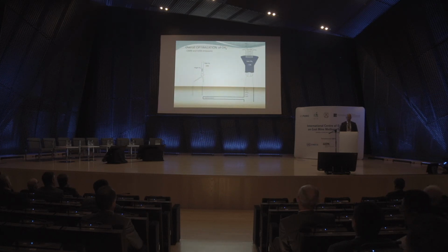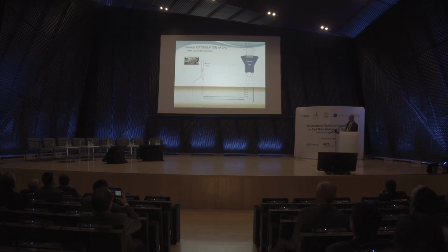So when you look at your installation, you want to optimize it. Well, you look at what concentrations and volumes you have in the drainage. You look at the concentration of the ventilation air. I would say you first look at installing gas engines, because that's the most cost-efficient way to use the mine gas. And then you look at, if you really want to reduce the emissions from coal mining, then you have to address VAM, because it represents like 70% typically.